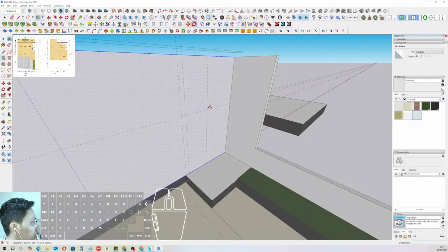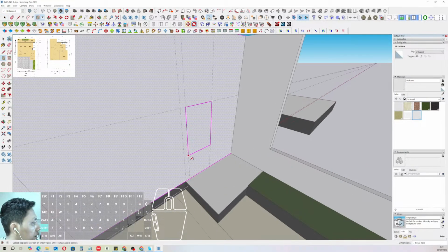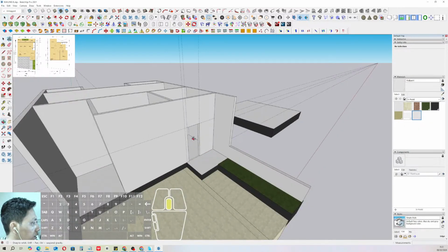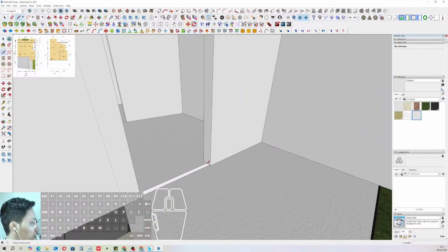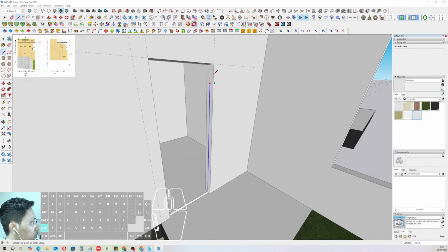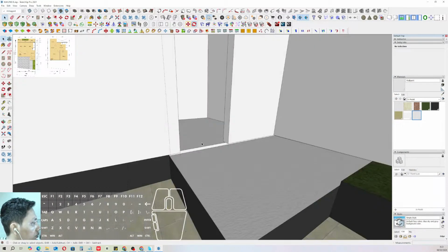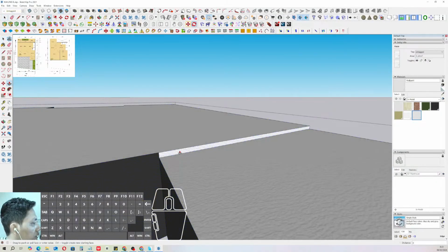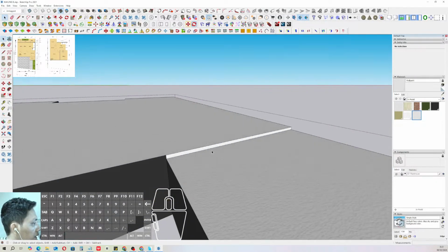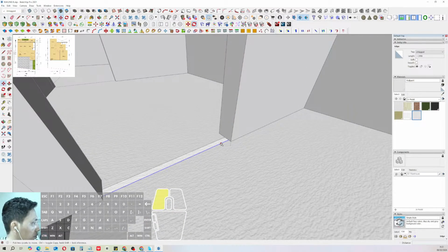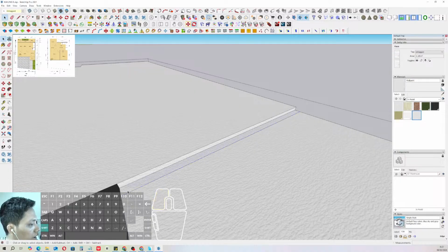Okay, and after that we can make the openings in here. We have to push it to the behind in here. Okay, then we can recheck again for the elevation between the ground floor to the top opening of the door opening in here. And then we can complete the uncompleted floor direction in here. We can just select this line, and then we can select move, tap control, place to this position. Then we got the surfaces in here,